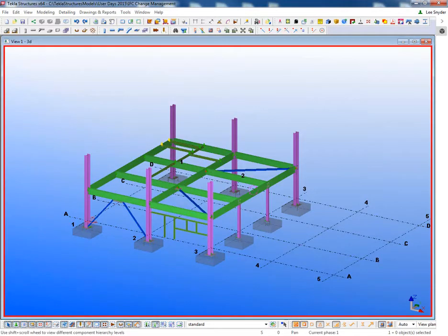So this first workflow is if you're just using Tekla internally and you wanted to use the IFC files to create a snapshot of your model and then use those to compare so that you can see what changes were made during a design change or a revision. And then we can also get a list or a report of that information that you can send along if you were going to bill somebody for that work, right?